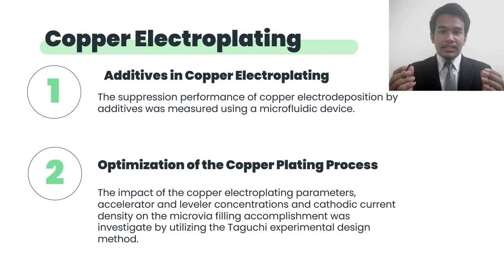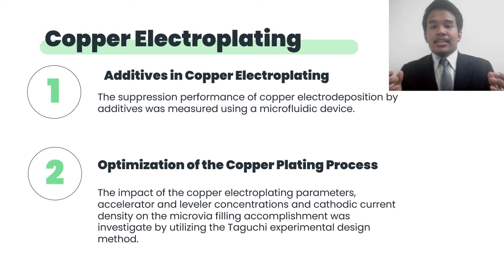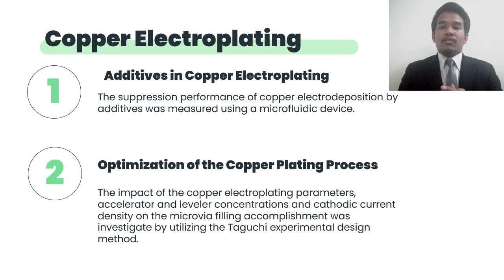Next is optimization of the copper plating process. The impact of the copper adsorption parameter, accelerator and leveler concentration, and contact current density on the microvia filling performance was investigated by utilizing the Taguchi experiment design method.